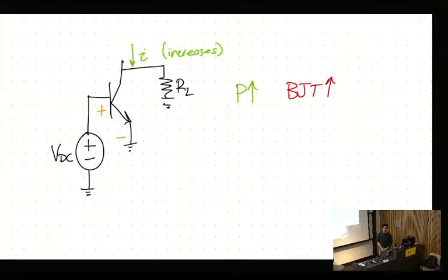And so what happens from here? Does the BJT calm down? What happens? So power increases, the BJT power, heat increases. And so in turn, what does this then increase? So if heat increases, the internal resistance remains the same. So the more heat, the more power dissipated. The more power dissipated, the more current we need to achieve the same power level. And then we're kind of just going in a circle. And we achieve what's called, I think Thorson calls it, thermal runaway.